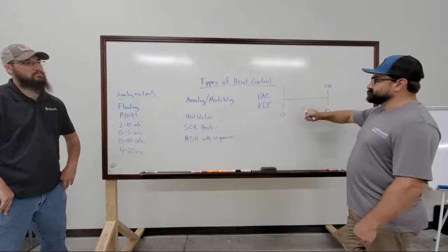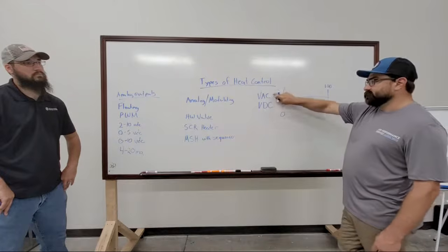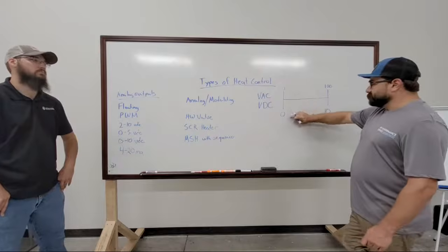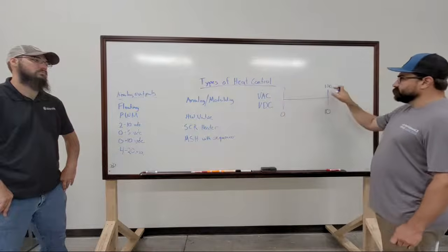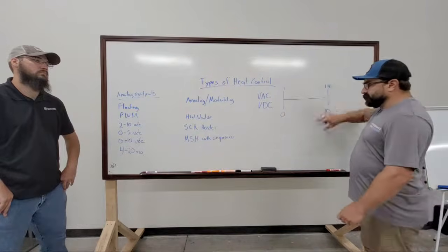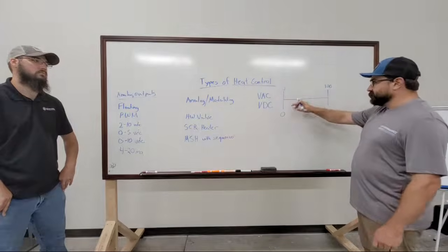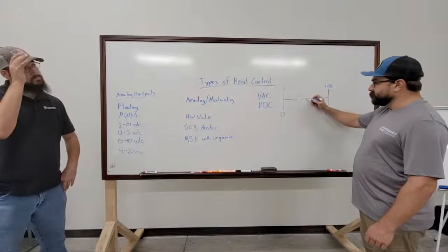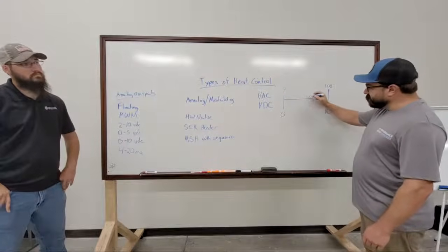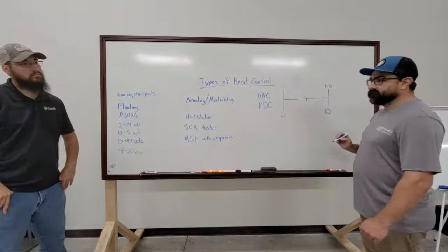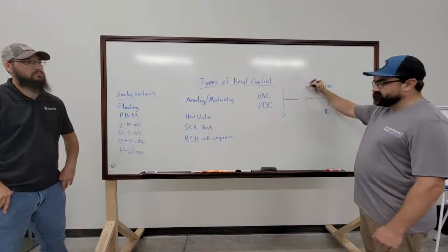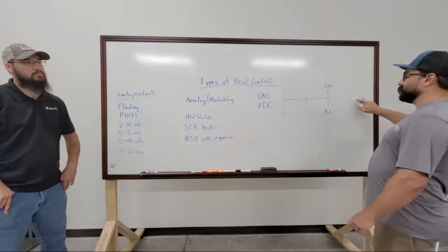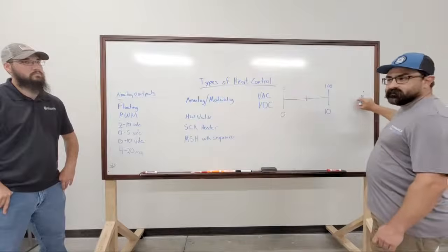So in order to do pulse width modulation, like I said, it depends on what you are controlling. It's very manufacturer specific as to what kind of signal and what range of voltage you are giving. But the basic way to think about it is, if you look at it in a 0 to 100%, a lot of them are over a second. Well, a second can be broken up into tenths. So if you want 50%, you would send whatever that thing is for 5/10 of a second, and that'll bring you to 50%. Then it drops out for the next 5/10 of a second, then would pick back up on the next 5/10 of a second, and then drop out.